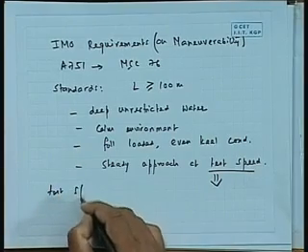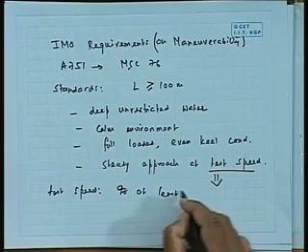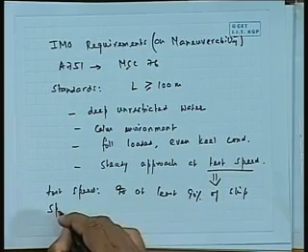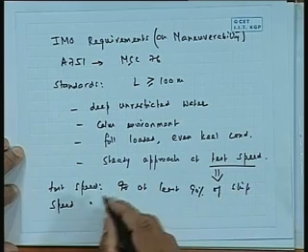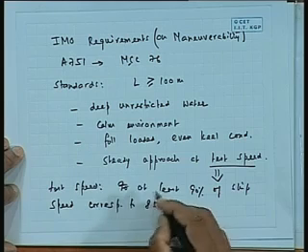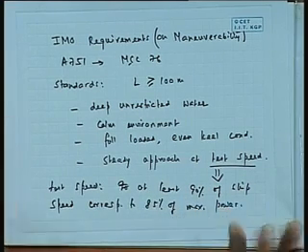Now there is a test speed given here, which is mentioned here. Test speed should be at least 90% of ship speed corresponding to at least 85% of maximum power. I'll tell you the reason for that.